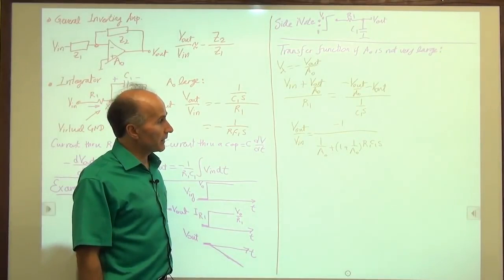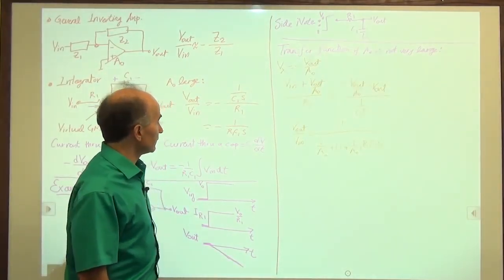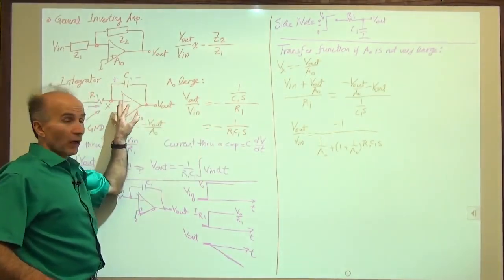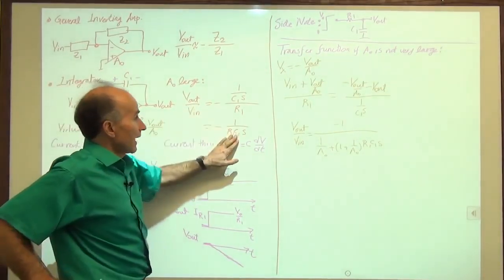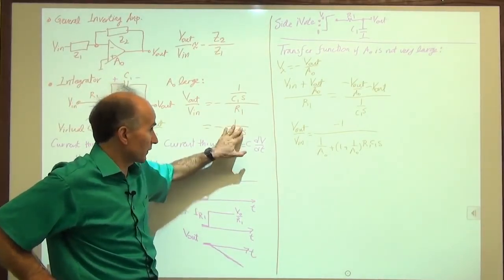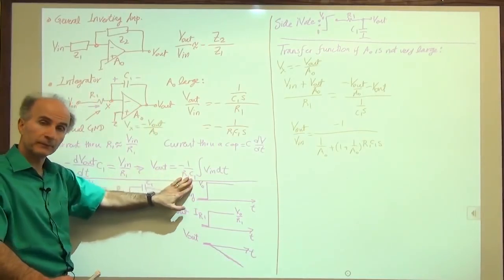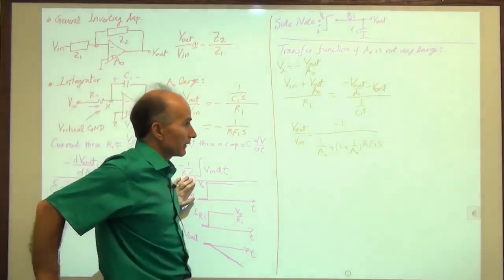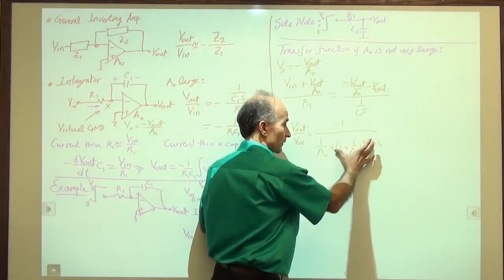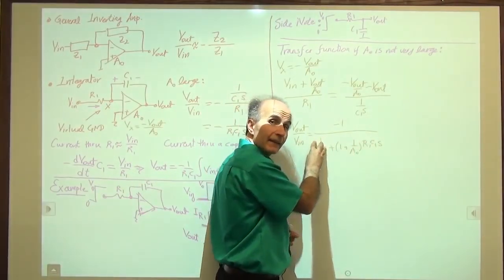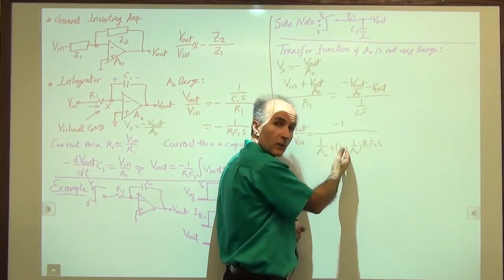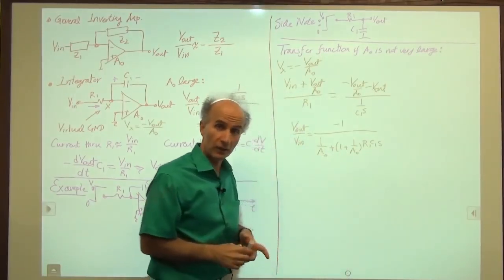All right, so what's interesting is the following. With an ideal high gain op-amp, this is an integrator. And we know that because if we take the Laplace transform of this, we get this. But here it's not quite that, because we have S with a coefficient, but then we have something added to it. So yes, this is a pole that is no longer at the origin.